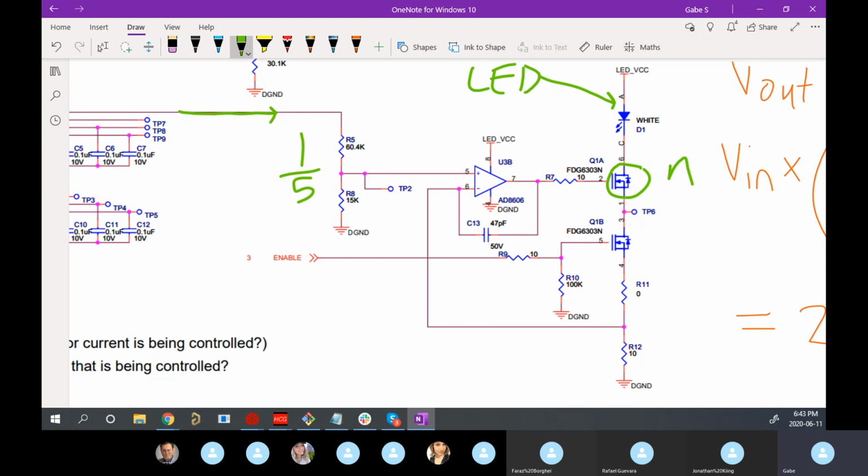So you're saying if output A is active with some voltage, then this LED will turn on. Is that right? If that's active, as well as the other MOSFET, which is the enable button. Nice. Good spot. So this is coming... usually when you see these two arrows on a schematic sheet, that means it's coming from a different sheet. So from somewhere else in the system, likely from your microcontroller. Very good observation. This is definitely something you should be pointing out.